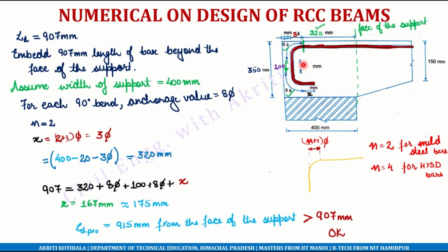If by chance the value was not sufficient, the development length which is required could not have been provided, then we could have extended this x to a greater value and increased the value of 100 as well, as per the permissible range here after excluding the covers.